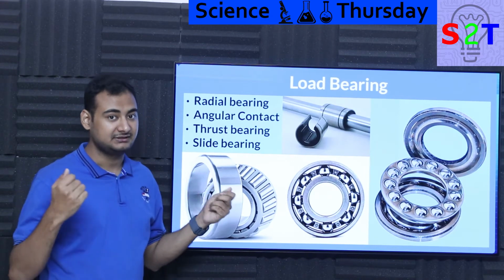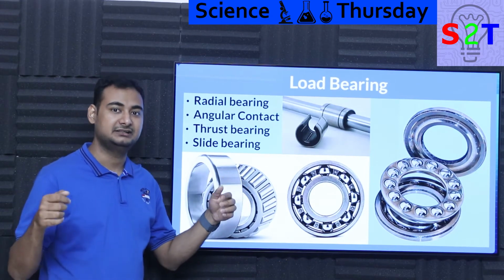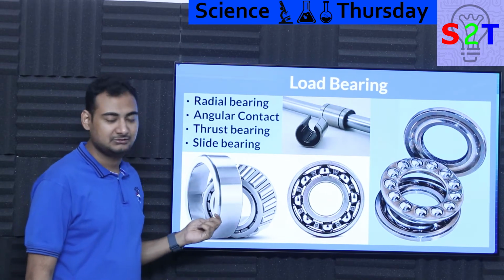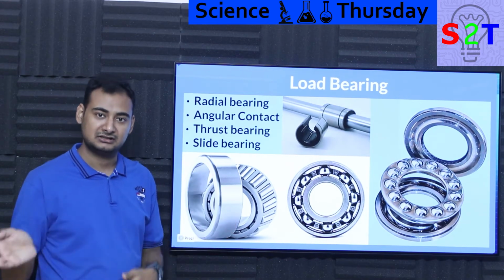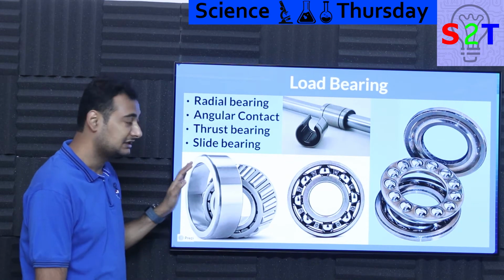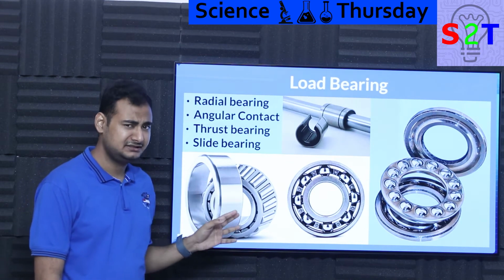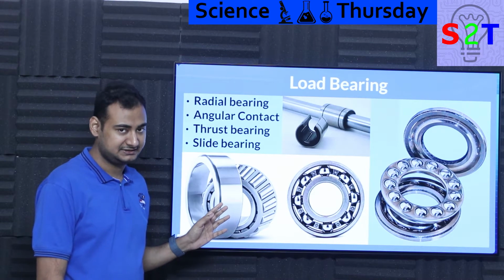It won't be damaged. And that's why you have to have two, because in some scenarios, like if you're taking a right hand turn, one bearing will be bearing most of the weight, and in a left hand turn the other will be bearing most of the load. So that's why angular bearings are found surprisingly in more places than you would realize.